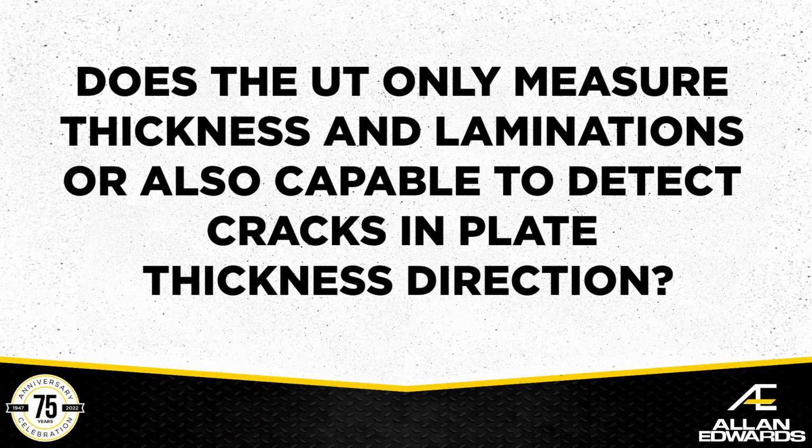Does the UT only measure thickness and laminations, or is it also capable of detecting cracks in the plate thickness direction? Yes, it is scanning thickness, laminations, cracks, any kind of voids, you name it. It will detect pretty much any defect, subsurface or on the surface.